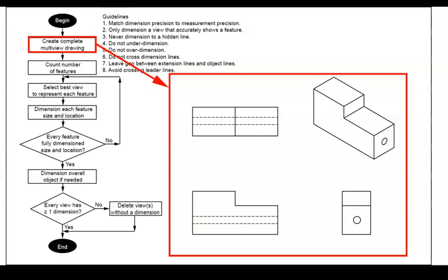So it's important that we match the numbers on our drawing to the measurements that we took it with. So if I measure something to be 0.125 inches, then whenever I draw it on the drawing, I write down 0.125 inches, not 0.12500 or 0.1. Those two are at different levels of precision, so we'll make sure that we keep them the same.